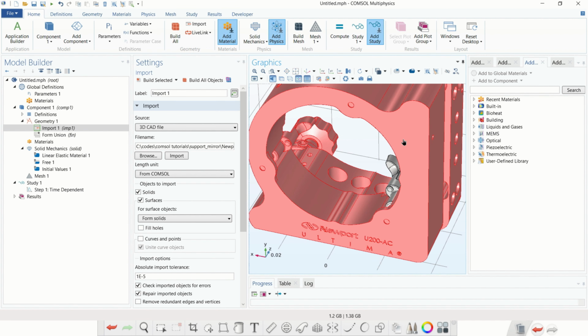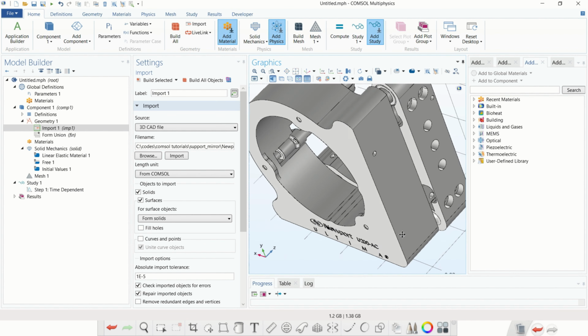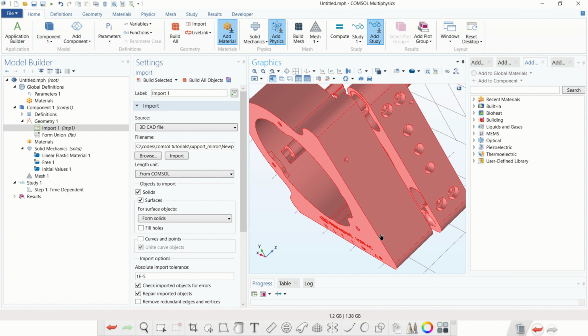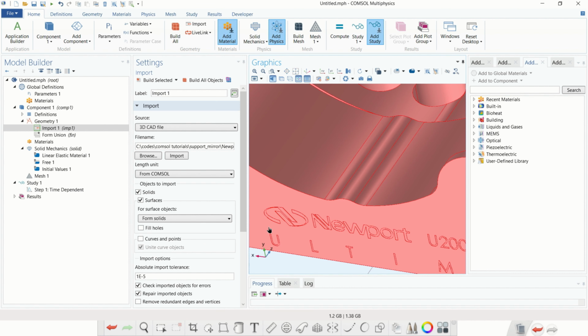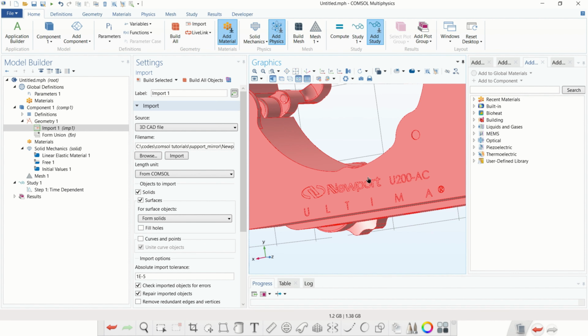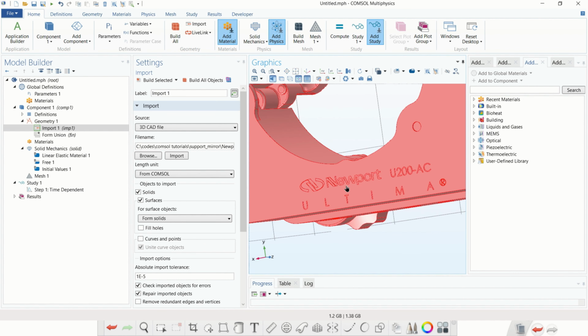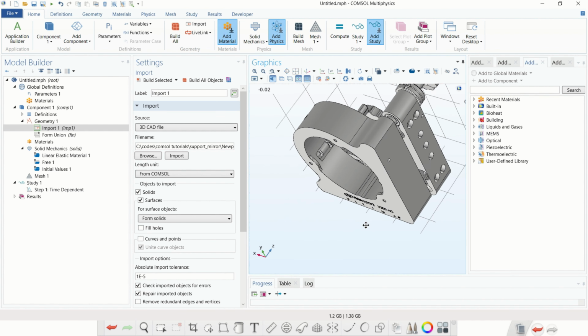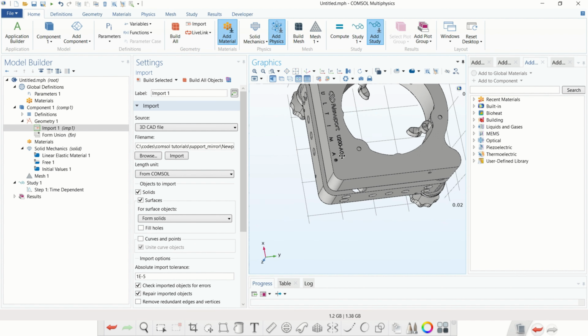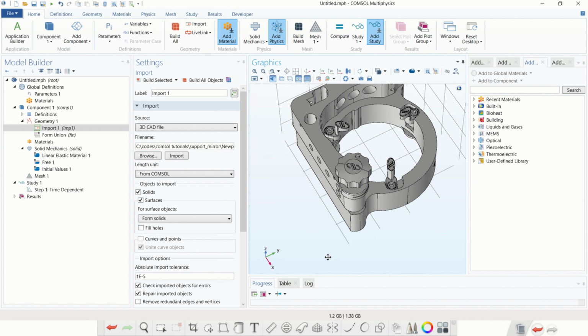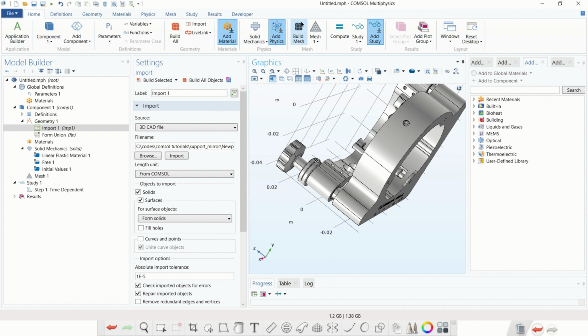So instead of defining the work plane that will contain this face, we're going to slightly offset such a work plane in order to avoid this engraved company logo that significantly complicates our geometry. In this way, we are going to simplify the geometry and repair our structure such that it can be easily used for meshing.